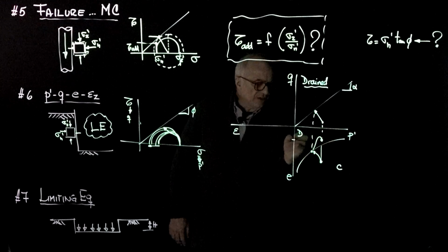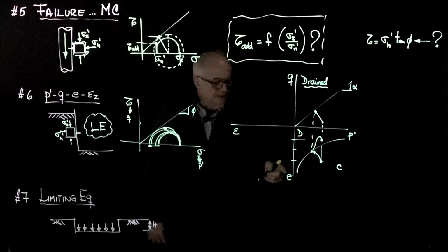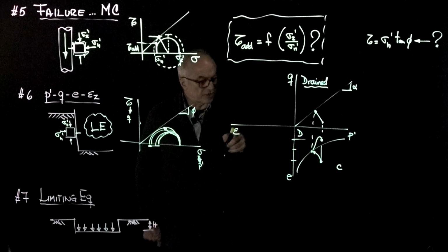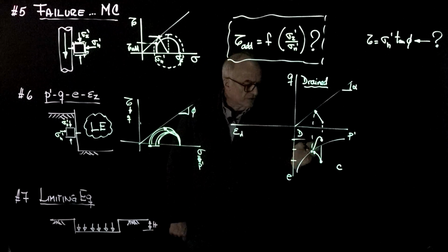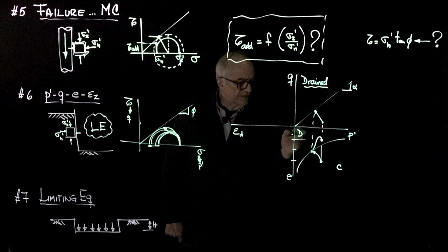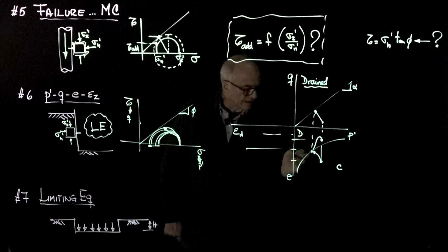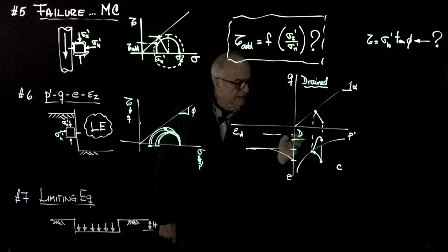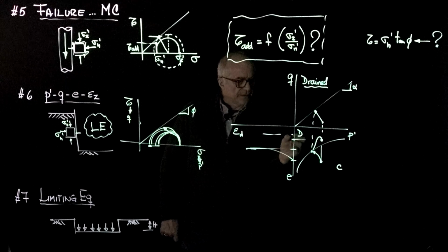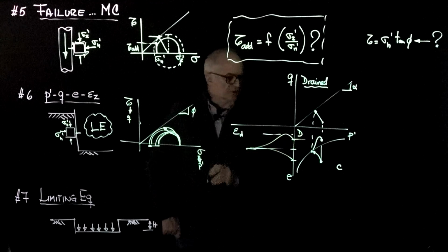So if we bring all these to the volumetric changes, which is void ratio, and deviatoric deformations, shear strain, this will plot something as follows. They will all end on this line. This one will do it contractively, this one may dilate a little bit, and then it goes like that.